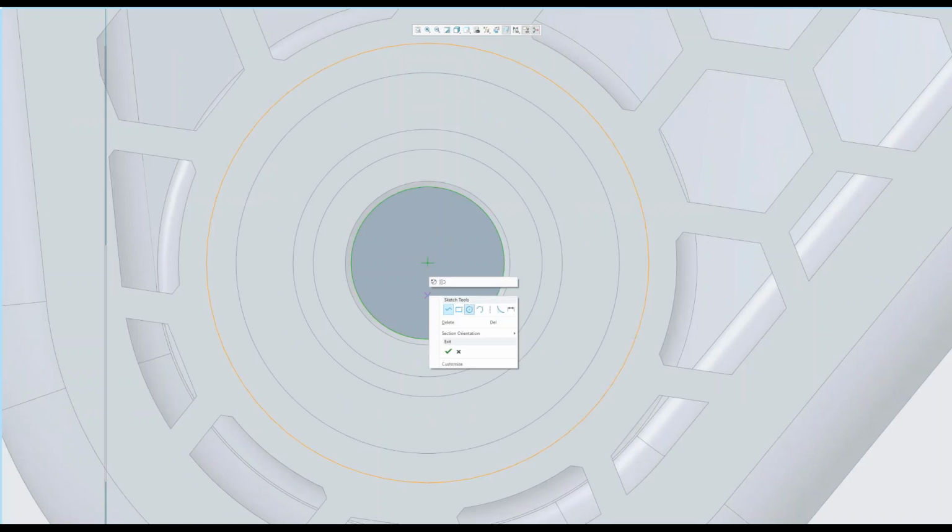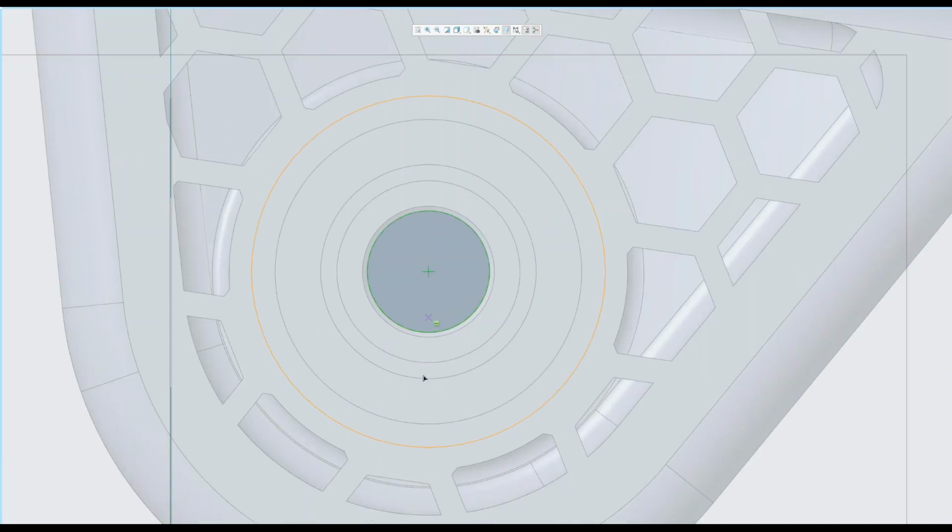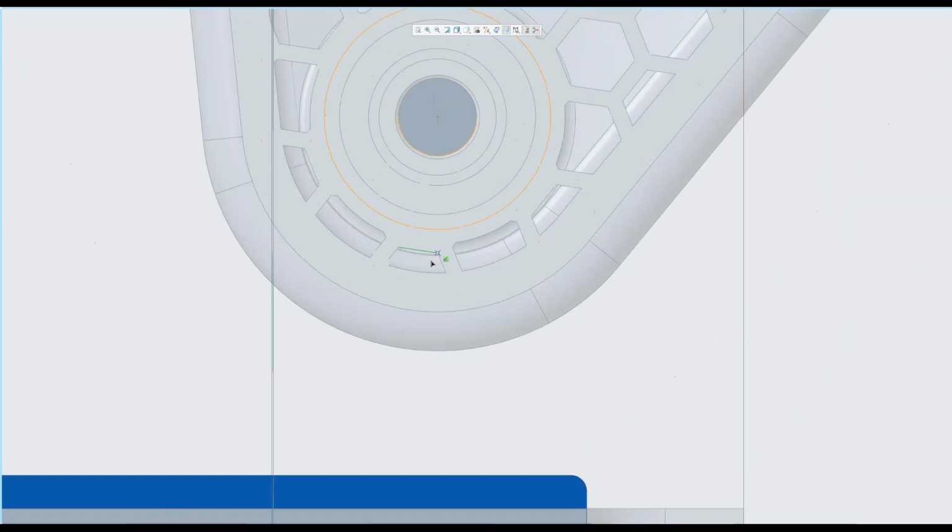I'm going to choose a line. Now, it's a little hard to see here, but as I'm following down with my mouse, I get a little blue dotted line, kind of a trailing line that indicates where the center of the circle is. So I want to keep that in line with where I'm going, so I can put in my line here, and I can automatically build in a tangent reference just by that snap click that I was talking about before.